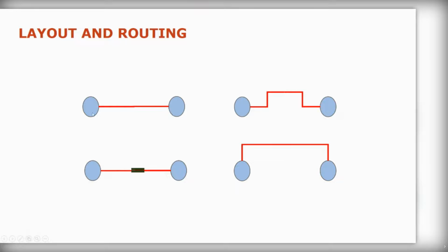That would be a very bad layout, and people who work in piping probably know that, especially if this is, two-dimensionally, just going straight. It doesn't have a step up or down, so it doesn't have any zigzags. Because what happens here, even the minimal amount of expansion in this line has nowhere to go. Either this pipe needs to buckle and start moving sideways, which is quite hard because, bear in mind, pipes naturally are very strong, which is a good thing in terms of, they don't need that much supporting because they're a strong shape, they're circular. But that also means they're not easy to buckle. They're not like slender members that will just simply move side to side. Or the other option is they're going to be pushing on the nozzles where they connect to the pressure vessels. And that's probably the most likely.